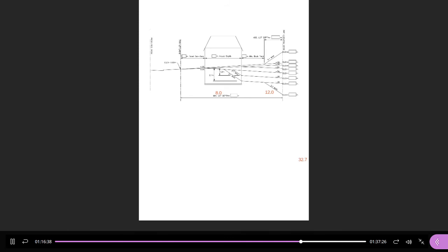So again, these are different thresholds. Now this one in the middle, the one I skipped, is just where the back split starts. Generally speaking, I usually ignore this, but it's worth noting. Usually if the front and the back have a vertical difference of about 4 feet or 1.2 meters, then you'll end up with a back split or a walkout. So this is a simple split. Anything between here and here is going to be a simple split. As soon as you get below that threshold, you're getting into back split territory, this area here.